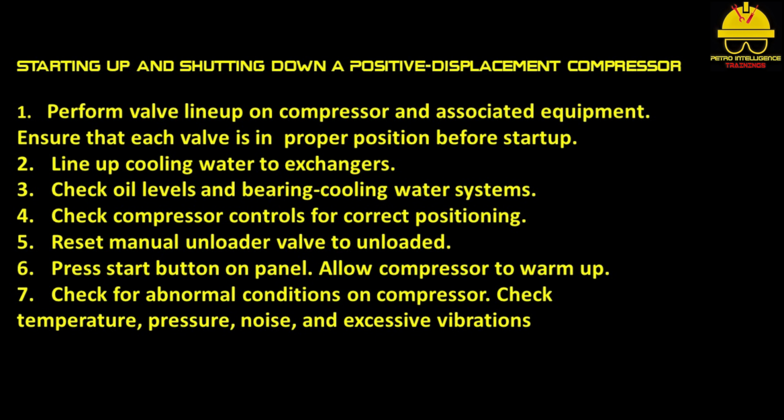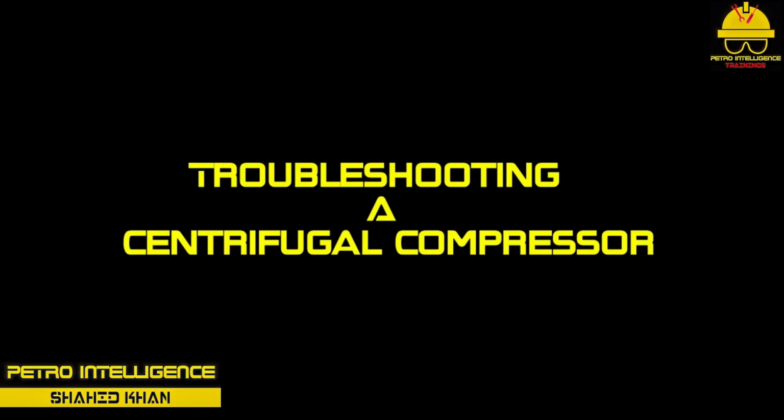5. Reset manual unloader valve to unloaded. 6. Press start button on panel. Allow compressor to warm up. 7. Check for abnormal conditions on compressor. Check temperature, pressure, noise, and excessive vibrations.